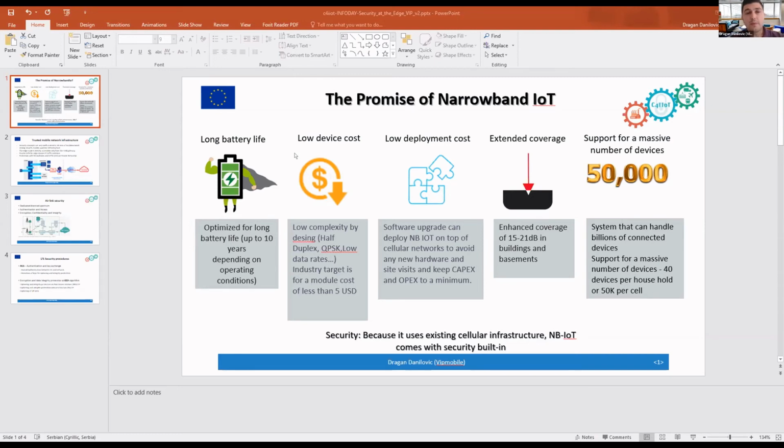Narrowband IoT is a new cellular radio technology specified by 3GPP in release 13. It is specifically designed for connecting edge devices with low bandwidth requirements using low power, while providing wider and deeper network coverage. Everybody knows that IoT can be used on any mobile technology, but there are great benefits from narrowband IoT, in the first place regarding power consumption. Long battery life is a must. Some studies and experiments show that even 15 years on one battery is possible, depending on operation conditions.